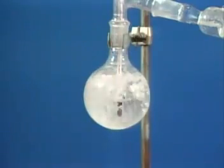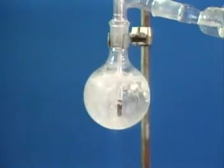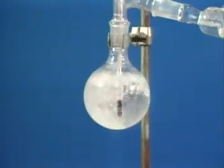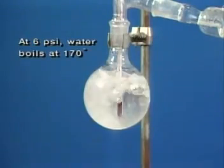Many distillation towers operate at or near atmospheric pressure. There are some distillation towers, however, that are designed to operate at pressures lower than atmospheric. These types of towers are called vacuum towers. Vacuum tower operation is based on the fact that pressure affects the boiling temperature of a liquid. For example, water boils at 212 degrees Fahrenheit at standard atmospheric pressure, which is 14.7 pounds per square inch, or psi, at sea level. If pressure is decreased to 6 psi, water boils at 170 degrees Fahrenheit.